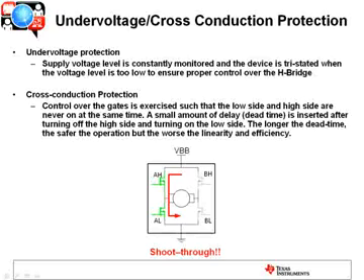Now, cross-conduction protection we talked about, that's really tied to the gate driver. That's ensuring that the high side and low side are never turned on simultaneously. And we mentioned earlier that this is accomplished by inserting a small amount of off time where the FETs are off. We call this the dead time. It's inserted right after turning the high side off, but before turning the opposite low side on, or the actual same low side on. Now there's a trade-off there.